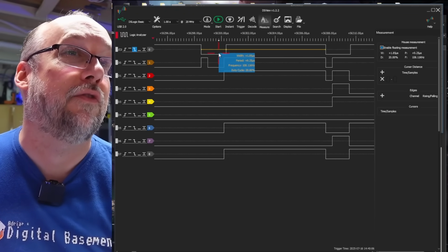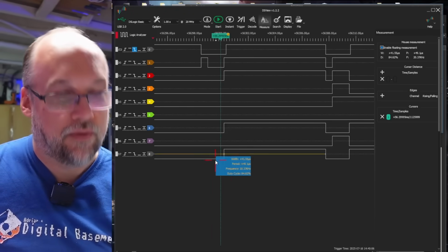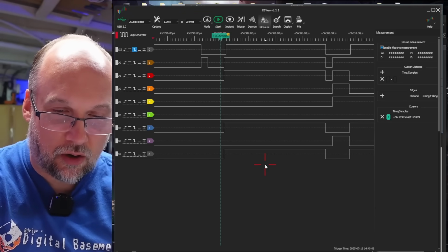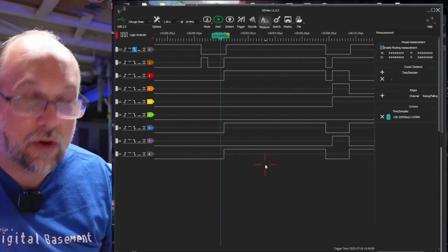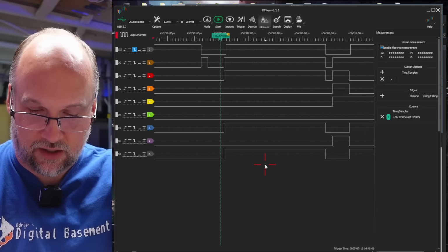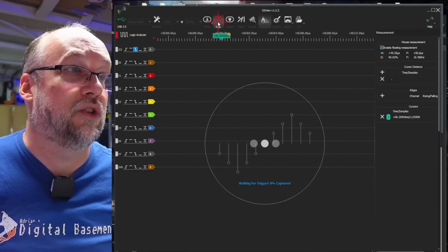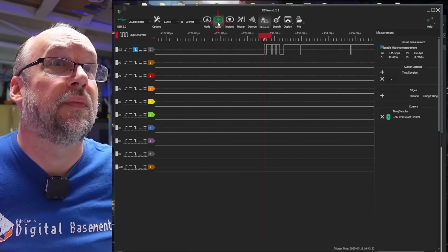So it looks like that first write looks like on this value here. Actually, you know what? To be honest, I should also be probing the write line. Let me hook that up. I think that'll give us a little bit more clarity on where that trigger edge is exactly. So I'm just going to redo a new capture.